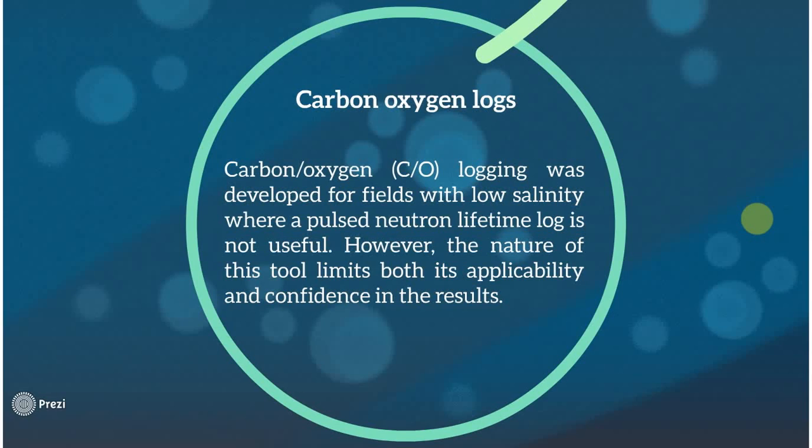To obtain a lithology compensation, most carbon-oxygen tools also record neutron capture spectra in which elements such as calcium, silicon, and iron reveal themselves. Neutron capture only occurs shortly after the neutrons have slowed down to thermal energies. Buffer timing separates inelastic carbon-oxygen spectra from capture spectra. Experience with carbon-oxygen logging has been uneven at best.